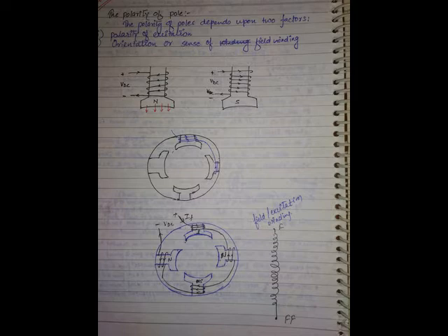These circulating currents, which are known as eddy currents, have no definite direction or destination and simply circulate within themselves. You want to reduce those eddy currents, so don't prefer solid cores. You have to laminate the core. If you take a simple cylindrical drum, because of the large cross-sectional area, as you know, the resistance is equal to rho L by A.